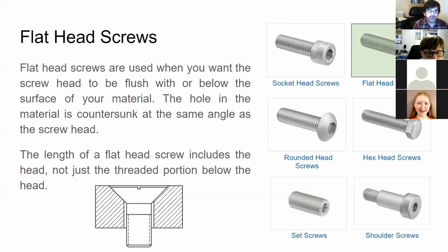Flat-headed screws are when you want the screw head to be subflush. You can drill with a type of drill called a countersink drill bit, and it will create this angular shape. You might see these on some products that we buy, but we don't stock countersunk screws. It's just more effort for the same thing.